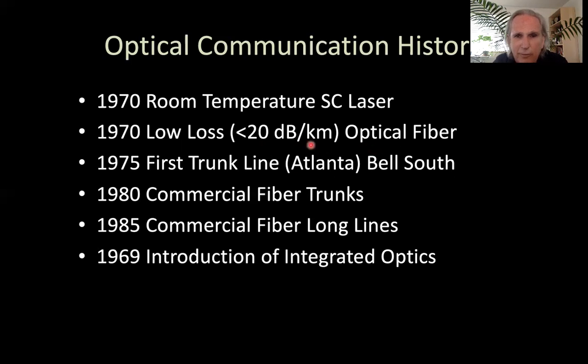That was less than 20 decibels per kilometer, but very rapidly, before this, it was about a dB per centimeter. Suddenly, there was a big change when they found out how they could use inside vapor deposition to get very clean fiber, and very rapidly, this went down to 3 dB per kilometer for multi-mode fiber, and soon after that, it went down to 0.2 dB per kilometer for longer wavelength single mode fiber.